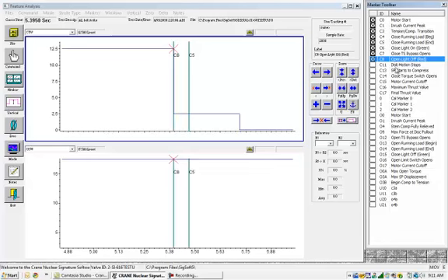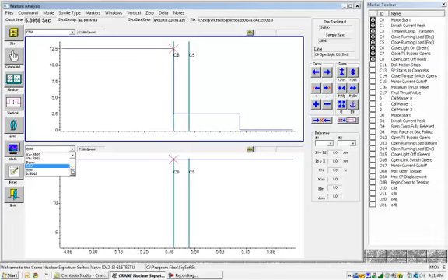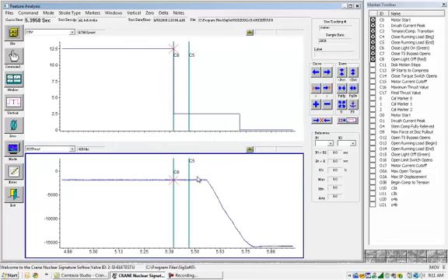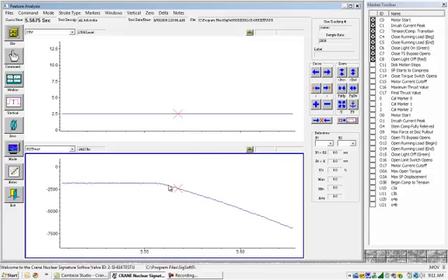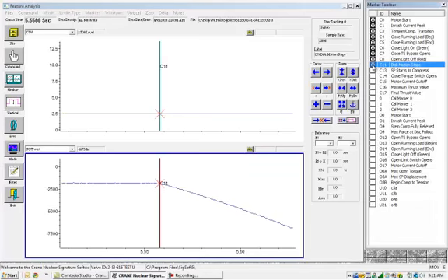Okay, so we got disc motion stop, so I'm going to bring up the strain gage thrust. And in this region is where the stem movement stops. Stem movement stops, hard seat contact. Both of those words can be used interchangeably.